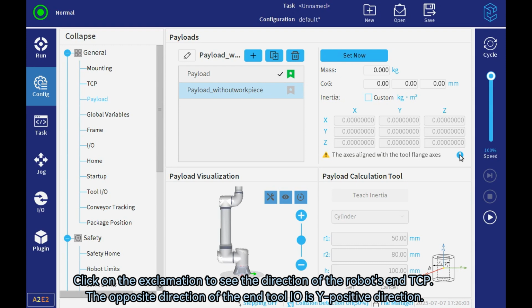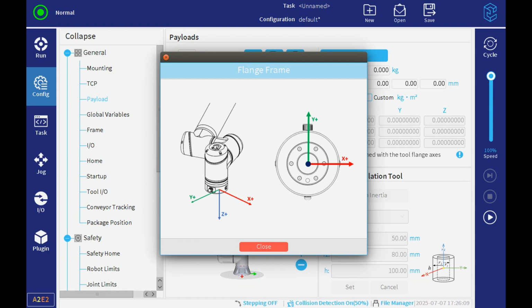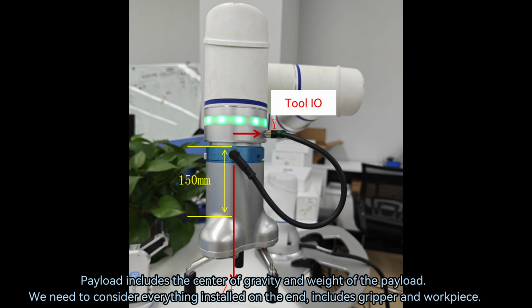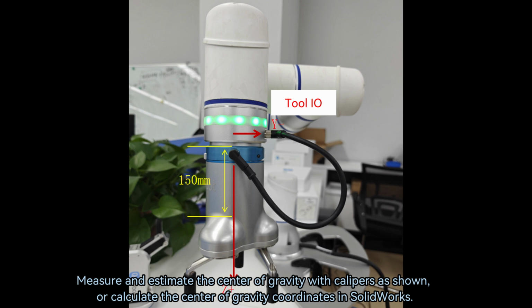Click on the exclamation to see the direction of the robot's NTCP. The opposite direction of the end tool I/O is Y positive direction. Payload includes the center of gravity and weight of the payload. We need to consider everything installed on the end, including gripper and workpiece. Measure and estimate the center of gravity with calipers as shown, or calculate the center of gravity coordinates in SolidWorks.